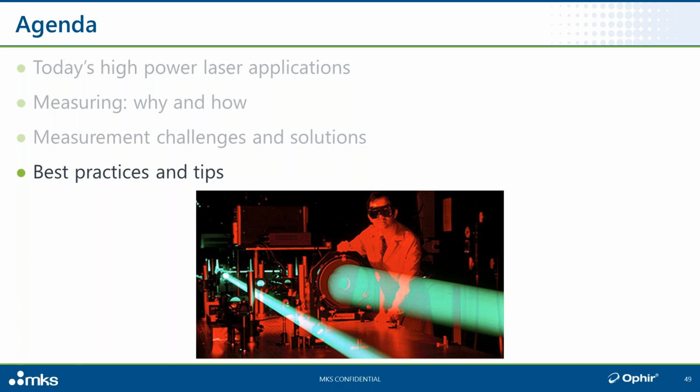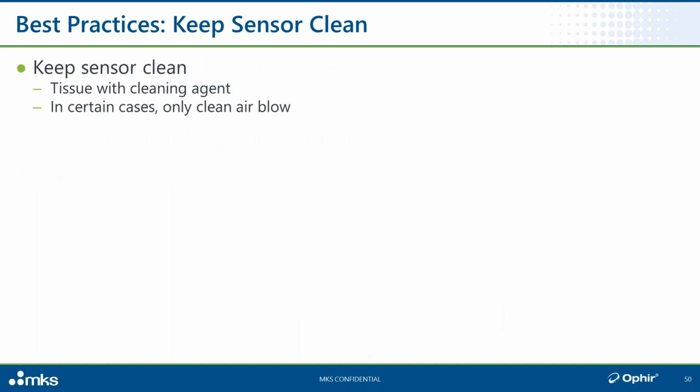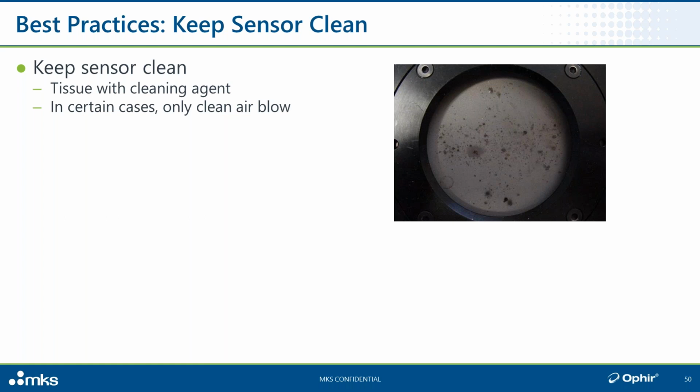Okay, let's talk about a few best practices, some black belt tips to get the best performance and the most successful, correct and accurate monitoring of the right parameters in your applications. Probably the most obvious one, and as obvious as it is, I cannot overemphasize it, is to keep your sensor clean.